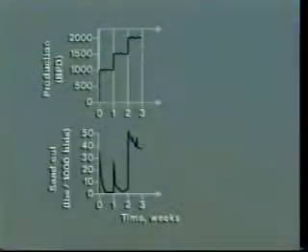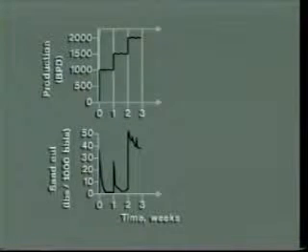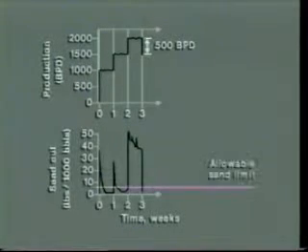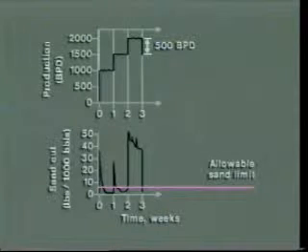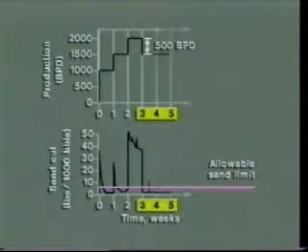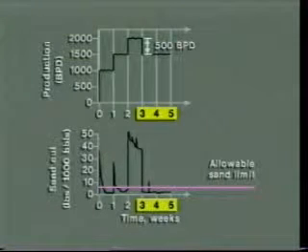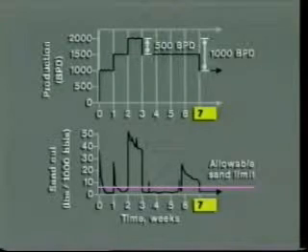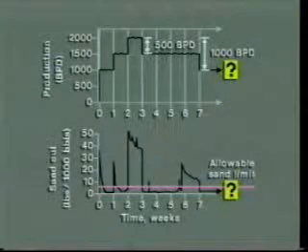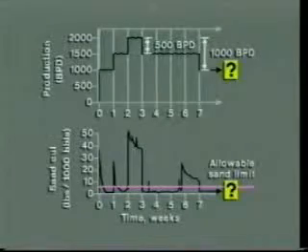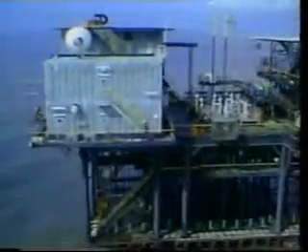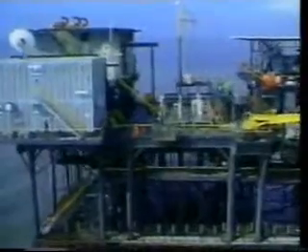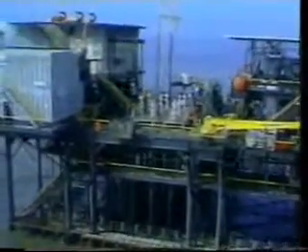As shown in this production test, production had to be reduced significantly to obtain an allowable sand limit. The choke bean that was selected only allowed acceptable sand production levels for 2 weeks, after which the well needed to be beaned back further. Based on this data, it is unknown whether the apparent natural arching effect displayed by this well will stabilize on this reduced choke. Only time will tell. However, if this bean size allows acceptable economics and sand stabilization for several years, then this method will have proven more favorable.